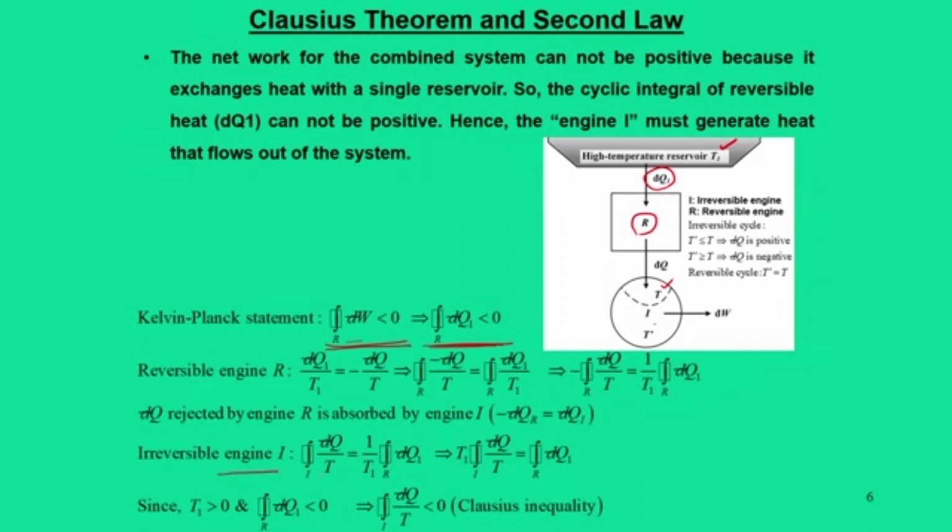So, let us evaluate the mathematical consequences. By definition we say ds equals heat transfer dqr by T, and for this process ds equals 0. Here dqr stands for the heat that happens in a reversible process, and as we always have for a reversible adiabatic process dqr is 0, so this is the truth. There are other possibilities. Finally, we can say that only this is possible, which means reversible adiabatic path.